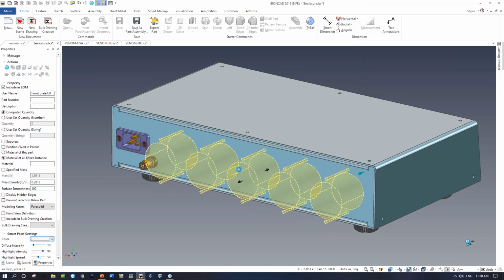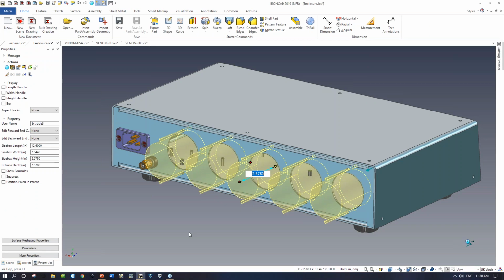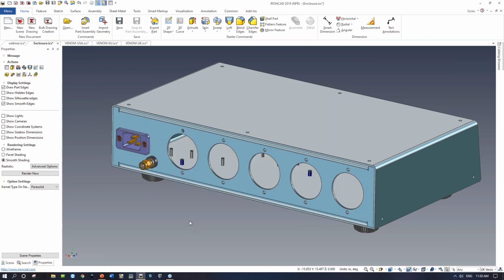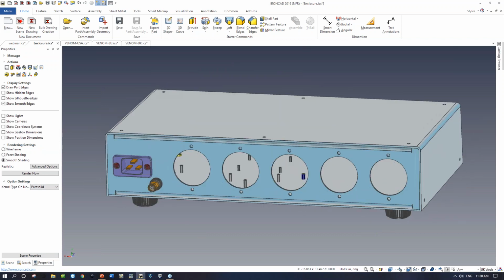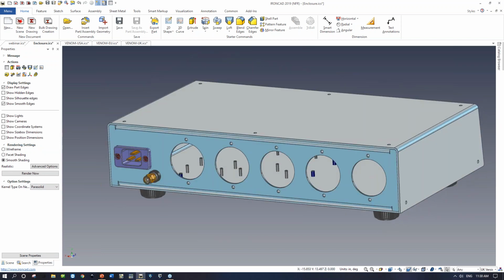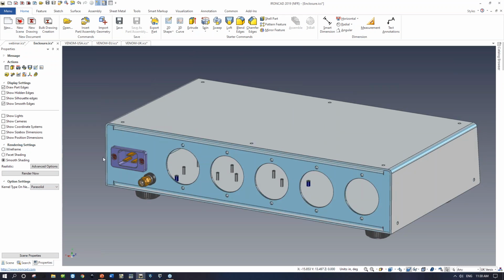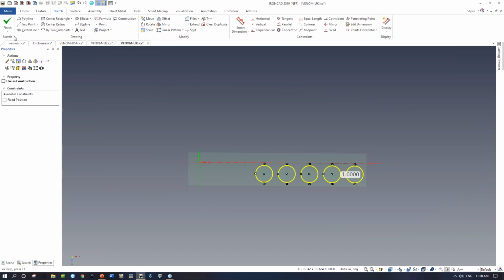Yeah, if you select that sketch and hit the actual extrude command on the ribbon, it'll go to the other command. That's what you're asking. That's what I wondered about. Okay, it's because I'm doing it up here. It's assuming. Yeah, and those are customizable, so you could actually put both commands up there, so you could choose which one you wanted in that action bar as well. Ah, very cool. Thank you for that. Yeah, because that's kind of what I wanted.